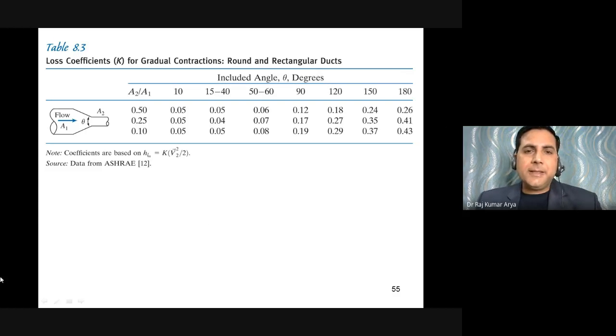So this is again the loss coefficient. This is called a nozzle. A nozzle is practically one where the inlet side has a bigger diameter and the outlet side has a smaller diameter. Either you can say the nozzle is just a small part, just this segment. If you have this end, then it is called a reducer actually. You are reducing the diameter, and you can reduce it this way, by tapering here.